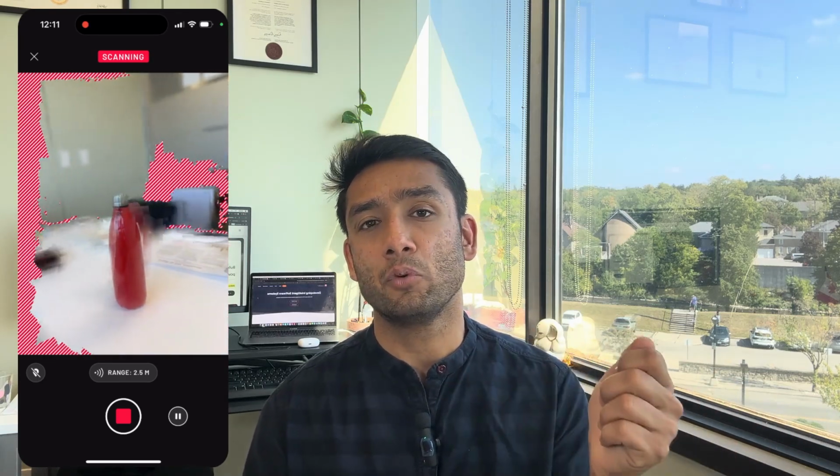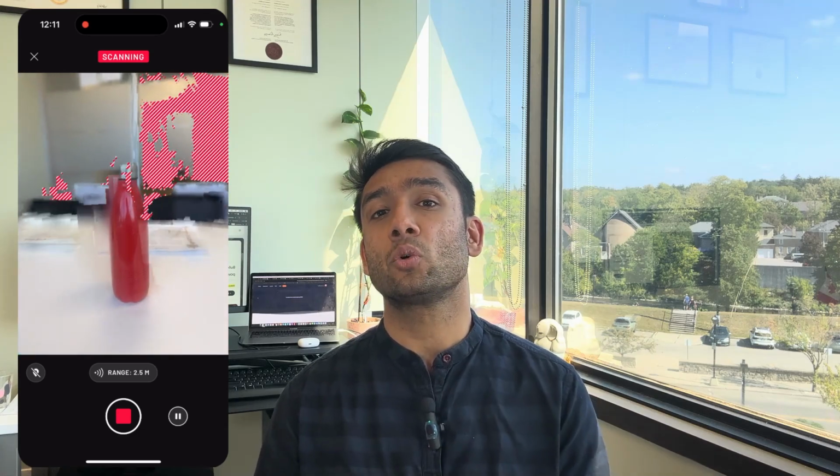So guys, for those of you who don't know, the way these 3D technologies usually work in the background, they take images of the object captured from different positions, different camera poses, and then they run a structure from motion algorithm in order to determine the camera pose, and also in order to help in the 3D reconstruction of that particular object. So that's why if you see me taking my phone around and moving it around that water bottle multiple times, so that it has enough data from different camera poses to be able to capture the water bottle from different angles and has enough information to then create the mesh.